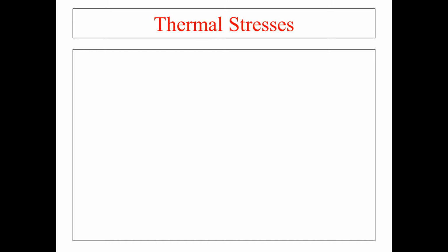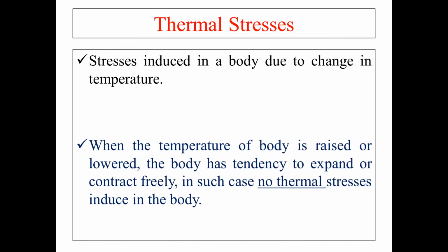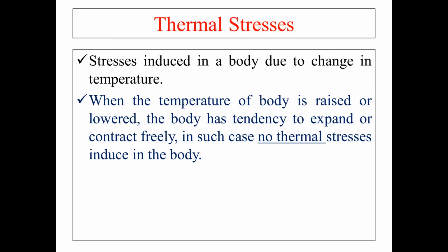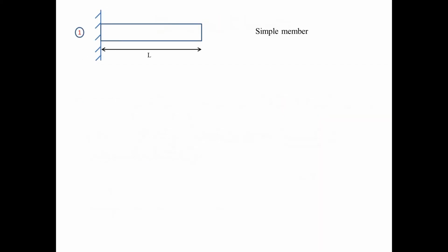So, to start the session, what is thermal stress? These are the stresses which are induced in the body due to the change in the temperature. When the temperature of a body is raised or lowered, the body has a tendency to expand or contract freely. In such cases, no thermal stresses will be induced in the body. But if the body is prevented from expansion or contraction, then thermal stresses are developed in the body.